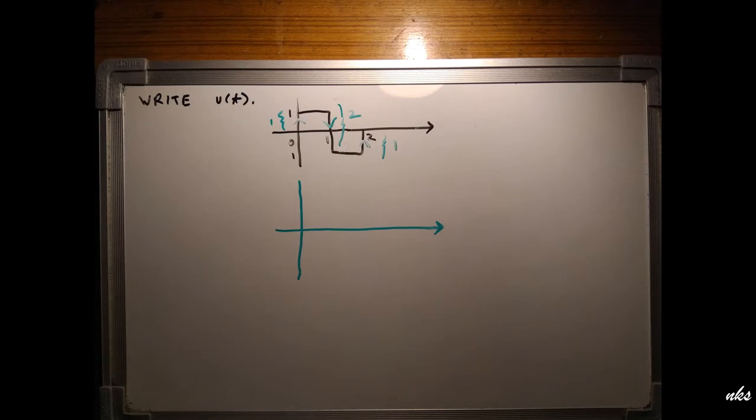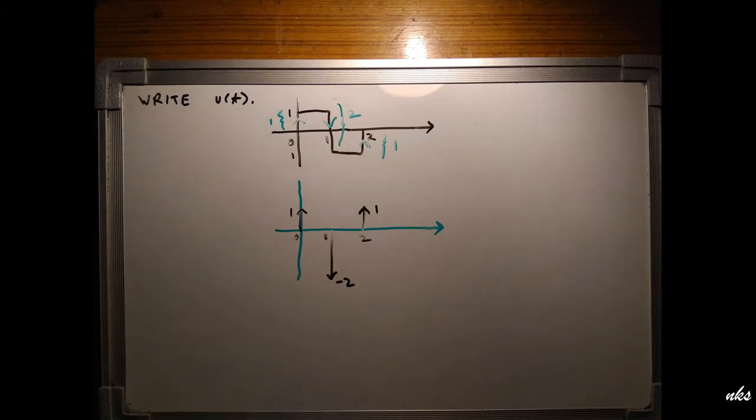So now what do I get after differentiating a unit step signal? I get an impulse signal, as shown on the screen. I hope you get this. I have already discussed these concepts. So now we can easily write the derivative from the given signal, which is delta(t minus 1), as the second impulse is at t is equal to 1, and the third impulse is at t is equal to 2, so delta(t minus 2). Now write the magnitudes, 1 minus 2 plus 1. So the function that we have written on the screen is x dash of t.